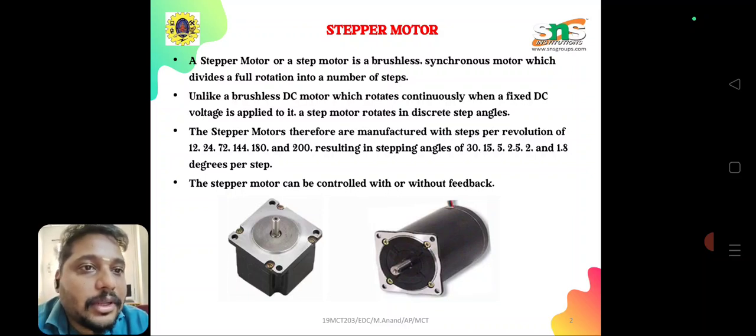Likewise, stepper motors are manufactured with steps per revolution of 12, 24, 72, 144, 180 and 200, resulting in stepping angles of 30, 15, 5, 2.5, 2 or sometimes 1.5 degrees per step. I think this is the very minimal step angle in our day-to-day life.